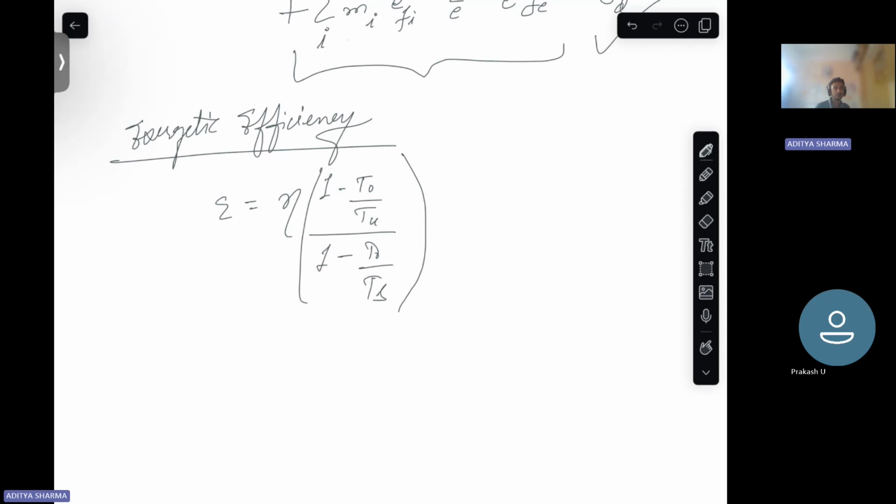And then there is one more element linked to it, that is some heat that we are getting from the source in the system is being dissipated. So that dissipation is taken into consideration using this eta, and then there's the rest of this term for this exergetic efficiency,